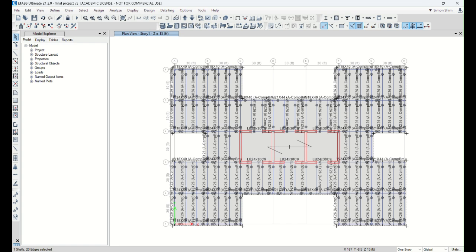Physically, just use a little bit of common sense. It's nothing crazy. Because this is a kind of composite metal deck, it should be sitting on top of these beams, right? But what about the core? At this point, I think don't worry about it. But I mention it since these days for high-rise buildings we use concrete as the shear wall system, right? Mostly the inside will be concrete construction, right?